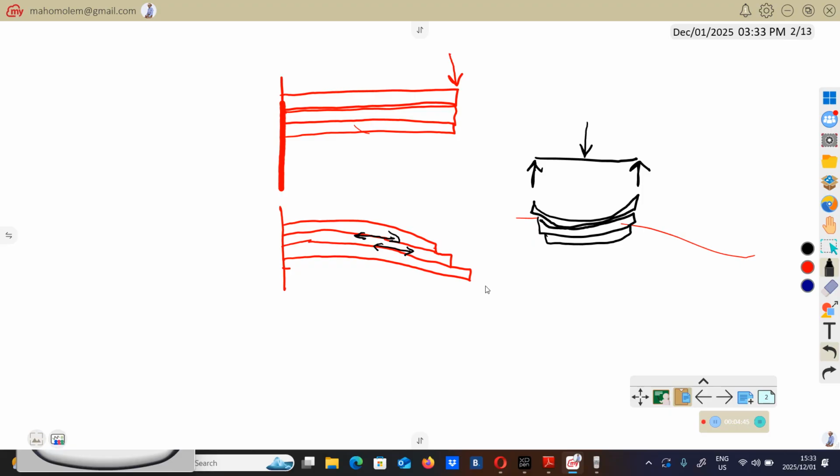Now back to our question, or let me just give some formulas that we're going to use along the way. Why are we calculating the horizontal shear stress? We have to find the horizontal force, or the magnitude of the force that will be generated here. That magnitude of the force that will be generated here, we're going to call the shear flow. We give it the symbol q.